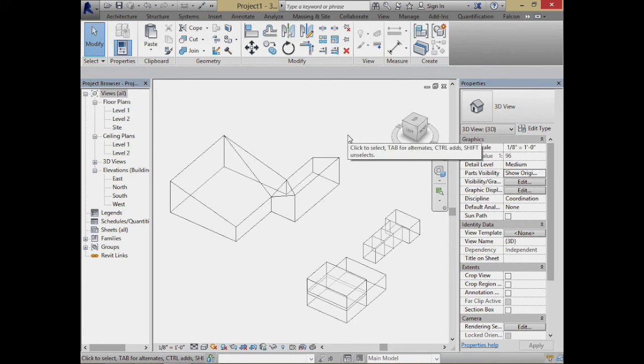It's okay to understand the building in terms of those really simple forms. And then really think about, for each of these different surfaces, which of those you're thinking about as being glazed, which of those are solid surfaces? And how is this all going to approach the whole notion of sunlight hitting it, what temperature performance is going to be like, where are the opportunities for ventilation? So you can leave it at this level. You can start saying, hey, I started my understanding in terms of trending it this way.